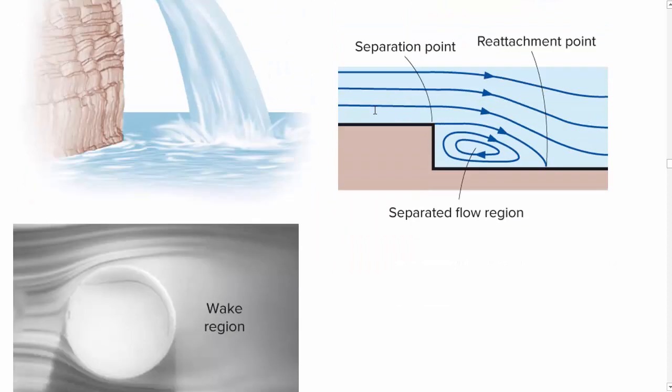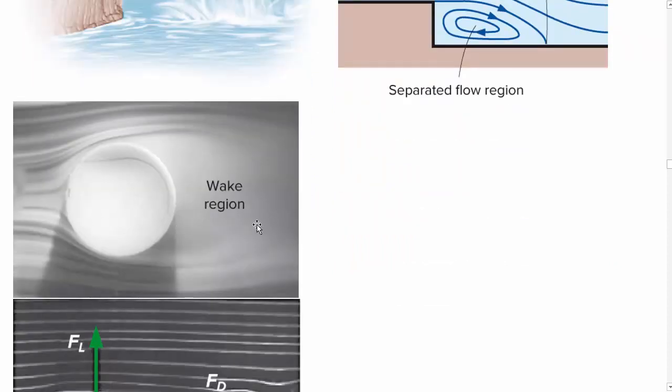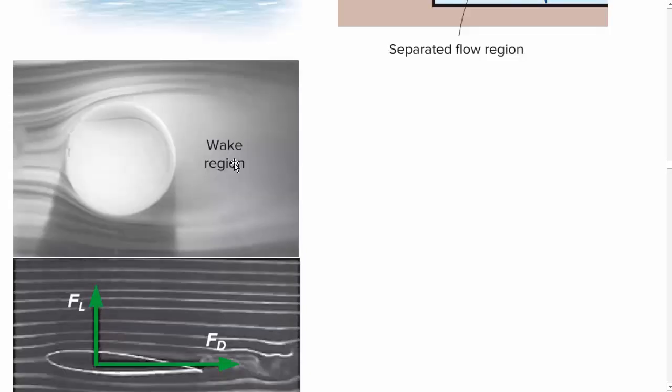So around an object, this is what creates a wake region, and the wake region ends up with a fair bit lower pressure than in front of the object, the side that's facing the fluid. Here the flow is going from left to right around this tennis ball, and the wake region's difference in pressure from the front of it causes a massive amount of form drag.